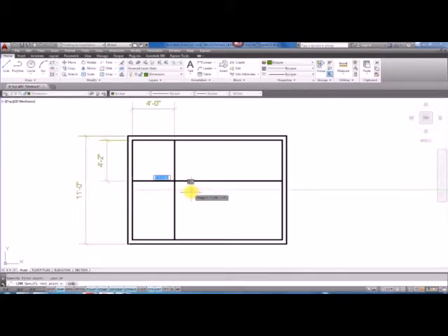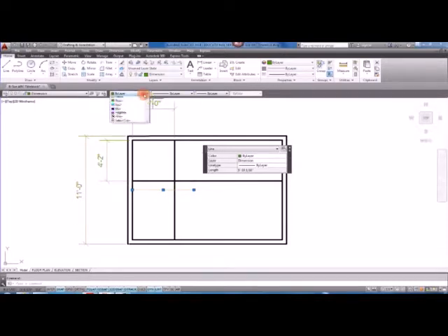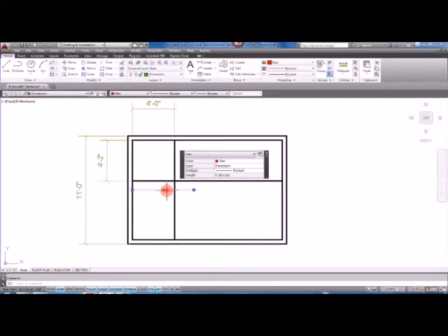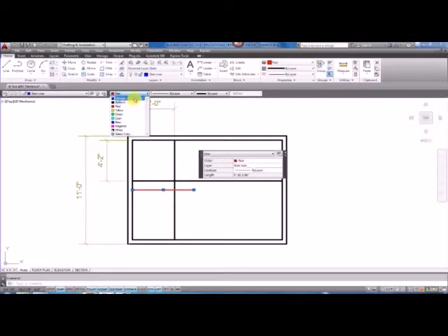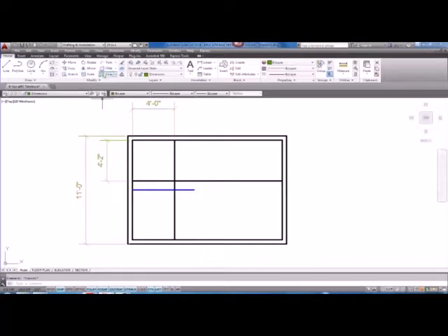So I'll get this midpoint line, and what I'm going to do is I'm going to color it red, and I'm going to put it on the stair riser layer. And so that is, in fact, I could probably not color it red. I think I'll just make this by layer, and we'll say that's our riser. And so we'll then offset that 11 inches to each side.